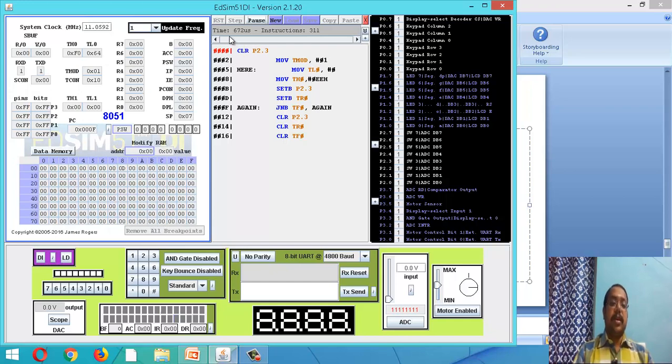Just we will see here now itself how many milliseconds, microseconds. It is 700-something microseconds. The number of instructions executed is around 357. So it will go on increasing to your required level. See, this is in micro, then it will come in milli, then you want 5 milliseconds.